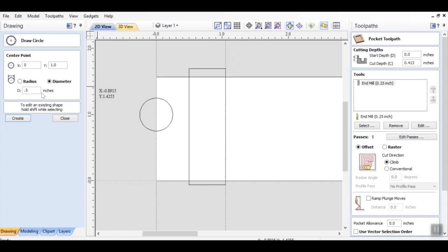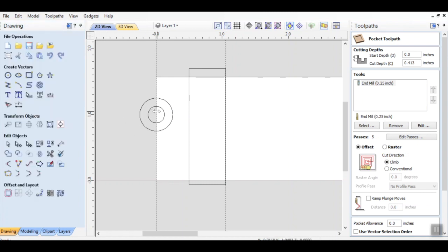Now, I want to make a diameter of 0.25, and that's the diameter of my peg. Let me close this. That's the diameter of my peg that goes in the hole. So I'm looking from the bottom of this after it's carved out, machined off. This piece here is my peg. This is the top handle I grab a hold of. And from here to there is a 1/2 inch, this material that I'm shaving away.